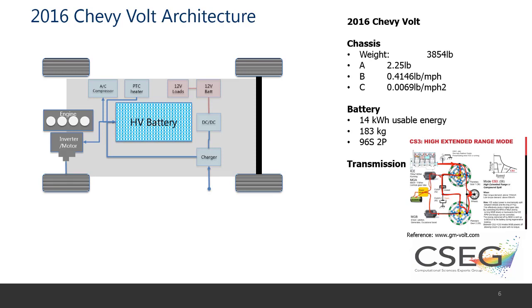And then secondly, as far as the hybrid technology is concerned, the 2016 Chevy Volt is Gen 2 and is one of the latest developments in hybrid technologies, with 2 planetary gears, 2 motors and a 1.4 liter IC engine. The 2 planetary gears give it 5 different modes of operation, 2 of them being EV modes and 3 of them hybrid modes. So it's quite a diverse and complex model to develop, and would also represent the state-of-the-art hybrid vehicle for us to evaluate different technologies on.